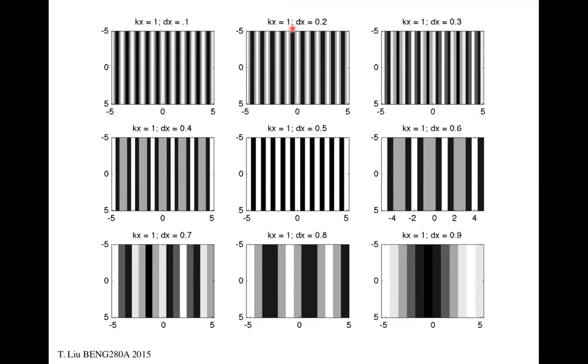What is the Nyquist criterion going to be? Here's 0.3. Delta x is 0.3, or approximately 3 cycles per millimeter is my sampling rate. Here's 0.4, so it's 2.5 cycles per millimeter. And here's delta x at 0.5. Recall my wavelength: I have 1 cycle per millimeter. Now I have 1 sample point every half millimeter, or 2 sample points per millimeter.